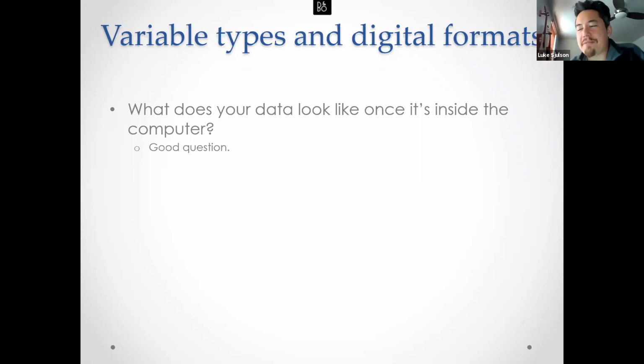Something I was going to talk about but didn't. So I guess the first thing to do is figure out what is the signal you're trying to measure, and what frequencies are present in that actual signal, right? People have done measurements of action potentials and found that action potentials don't occur on megahertz. There's no nanosecond stuff going on in an action potential. The ion channels have a certain rate that they open and close at. People have measured and determined that action potentials don't really have any frequencies above 8 kilohertz.